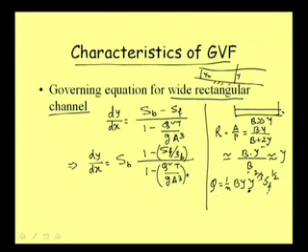Because the same discharge Q is flowing here, when we write for Yn, we can write 1 by n, b Yn, then hydraulic radius for normal depth condition is also Yn to the power 2 by 3, and this we can write as S_B to the power half.